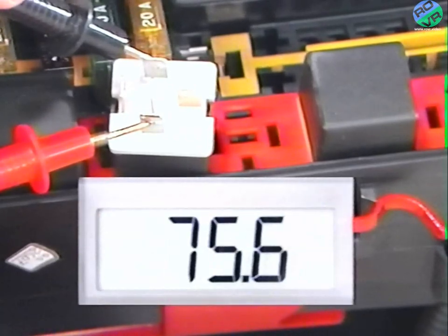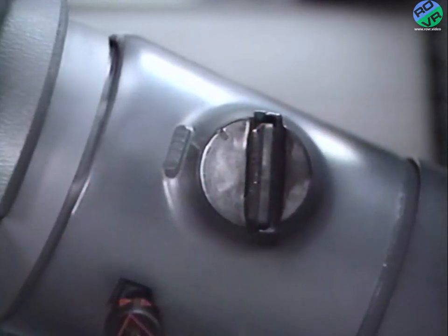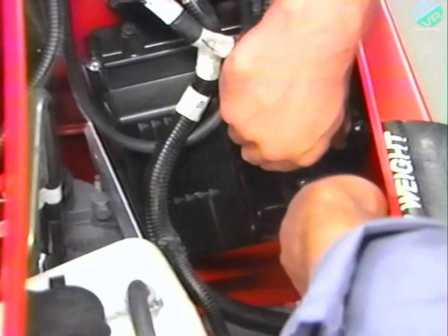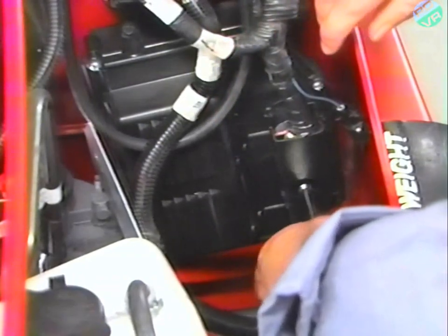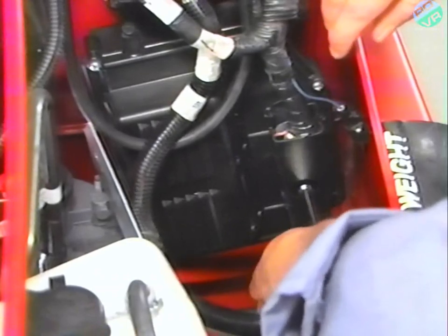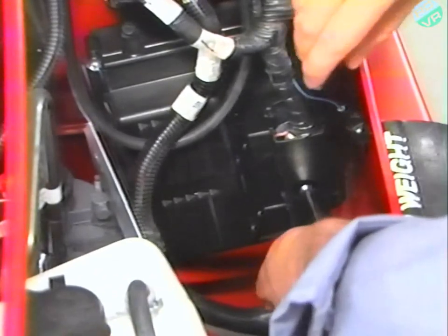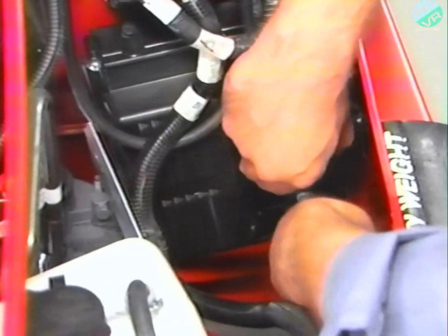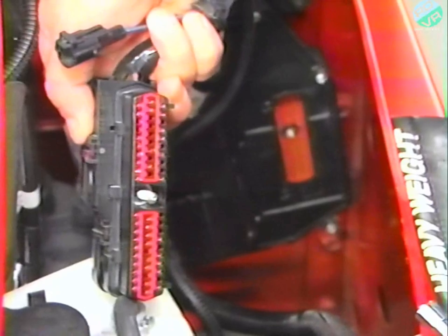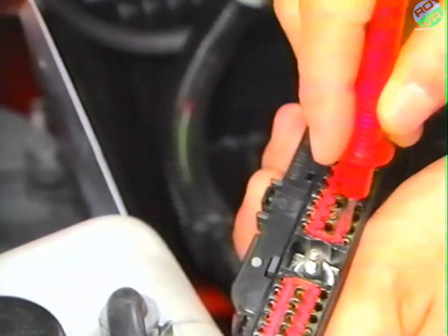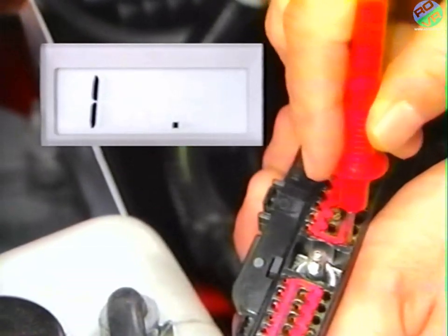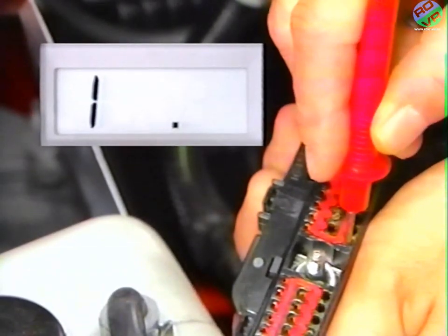But if the relay resistance was below 100 ohms, turn the key to the off position, then disconnect the engine controller connector and inspect the controller and the connector as shown earlier for damaged pins or pushed out terminals. If the connector is damaged, repair it. If the connector is in good condition, test NS10A instructs you to use an external ohm meter to check the resistance of the orange wire with the dark green tracer.